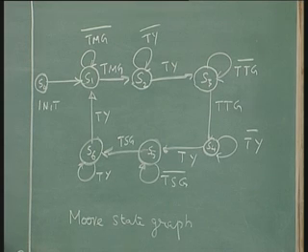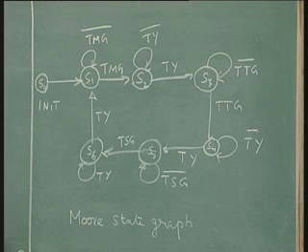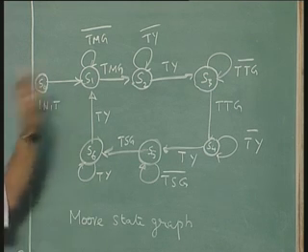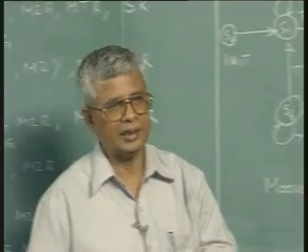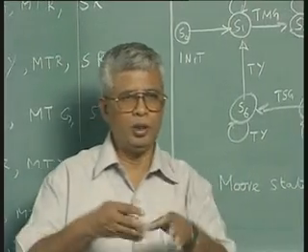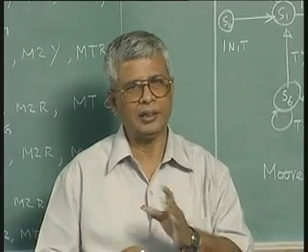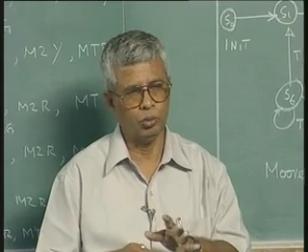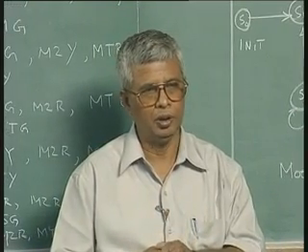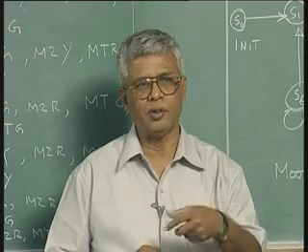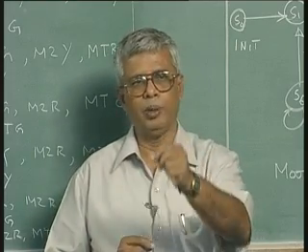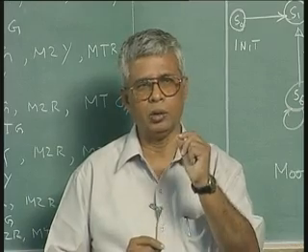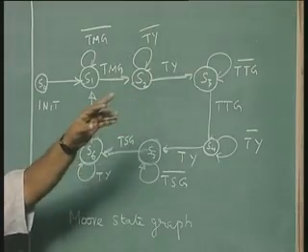So, you have a system clock which is counted, and when a particular count is reached we will call it TMG. So, we define for this given time, depending on the time, TMG let us say is 1 minute, 60 seconds. Assuming you have a clock period of 1 second, which is too large, I am just saying for example, 60 such clock cycles will exist for TMG. So, you keep counting, when 60 counts are reached, TMG becomes on. When TMG becomes on, the circuit goes from this state to this state, that is what I mean.